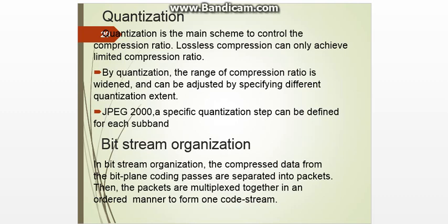After the coding, we perform the bitstream organization. In the bitstream organization, the compressed data from the bitplane coding passes are separated into packets. Then the packets are multiplexed together in an ordered manner to form the one code stream, that is the output bit stream.